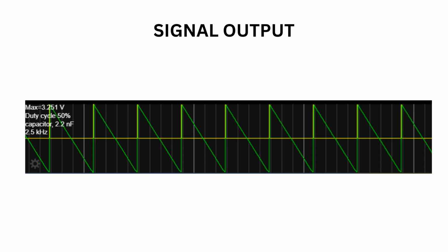Because the waveform remains above 0 volts, it contains a DC offset, which is consistent with the A over 2 average value derived earlier in the Fourier series analysis. The near linear slope of the falling edge indicates that the capacitor is discharging at an almost constant rate, while the sharp rise corresponds to a fast discharge path controlled by the switching elements in the circuit.